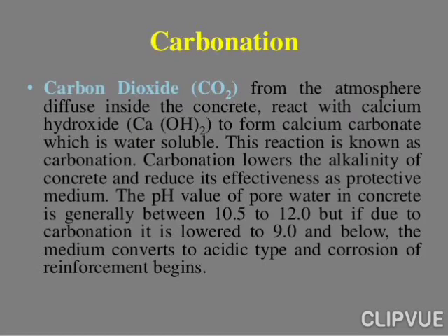What is carbonation? Carbon dioxide from the atmosphere diffuses inside the concrete and reacts with calcium hydroxide to form calcium carbonate, which is water soluble. This reaction is known as carbonation. Carbonation lowers the alkalinity of the concrete and reduces its effectiveness as a protective medium. The pH value of pore water in concrete is generally between 10.5 and 12, but if due to carbonation it is lowered to 9 and below, the medium turns acidic and corrosion of reinforcement begins.